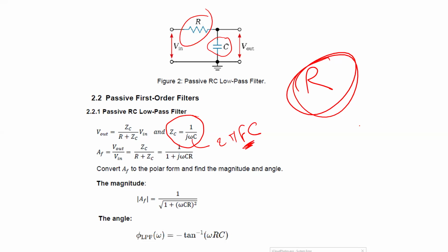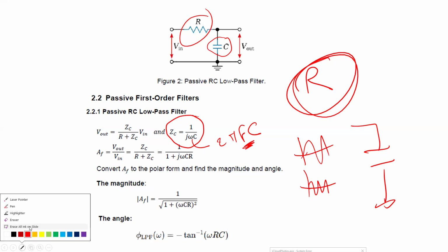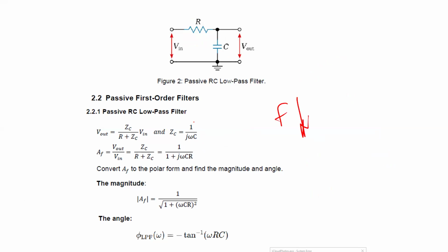That means if you have a capacitor and signals with different frequencies, they are going to see different impedance, different resistance. This is a fact. I'm going to use this fact, the main underlying idea for filters. If the frequency is very small, at very, very small frequencies, you can see from the formula that the impedance will be very close to infinity. That means it's an open circuit. So some frequencies are going to see open circuits. They are not going to pass.